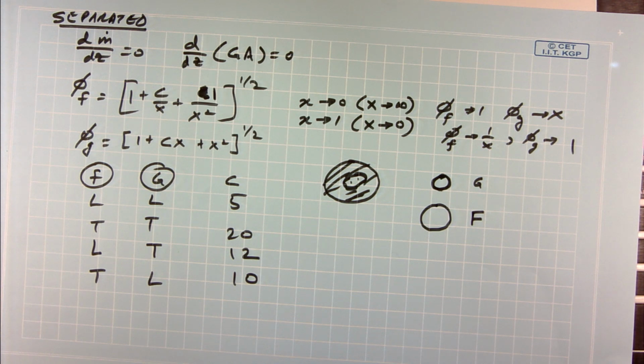Now, what is constant for these two pipes? Nope. Flow rate is not constant, it is pressure drop. So, at the inlet and outlet of each of these tubes, the pressure is the same, or the drop in pressure in both the tubes should be the same for the separated flow model, isn't it?